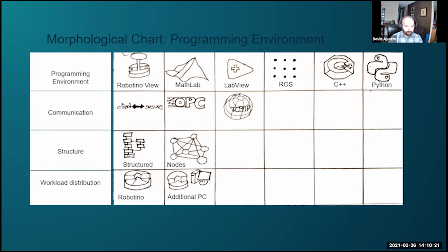Next, we had to choose the best way to interface between the Robotino and the ABB robot controller, and we've used socket programming functionality that was built into the ABB to communicate with ROS on the Robotino from the ABB controller. And this then steered us into ROS's node-based system, in which we use Python to control synchronous and asynchronous data streams between different parts of our project. And this also made it much easier to collaborate by breaking tasks into smaller parts.